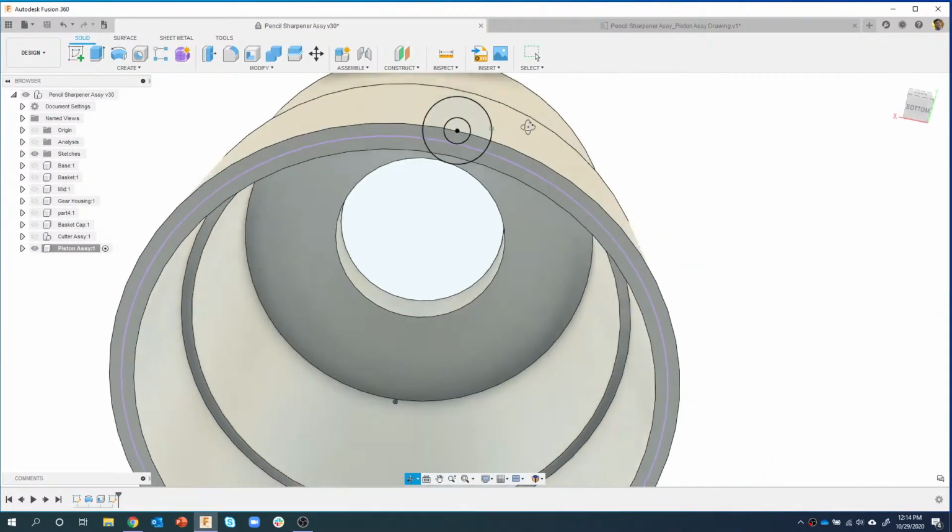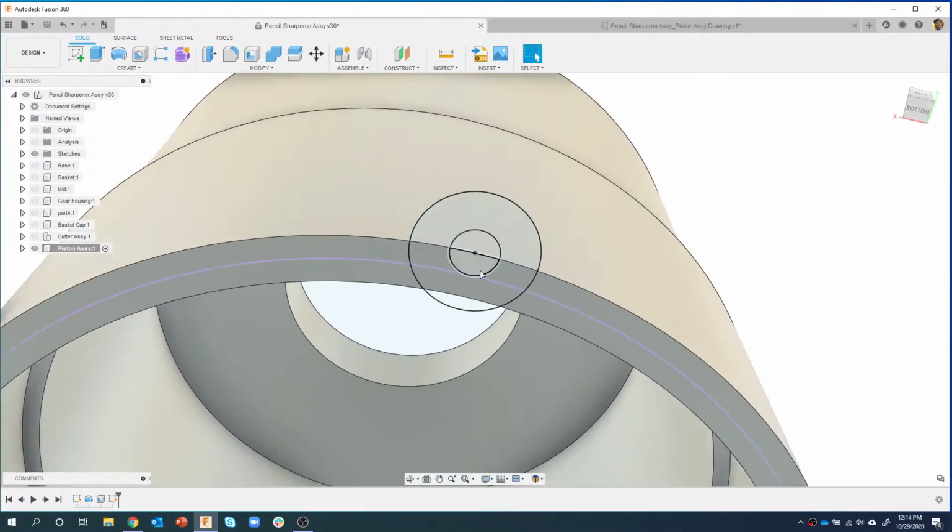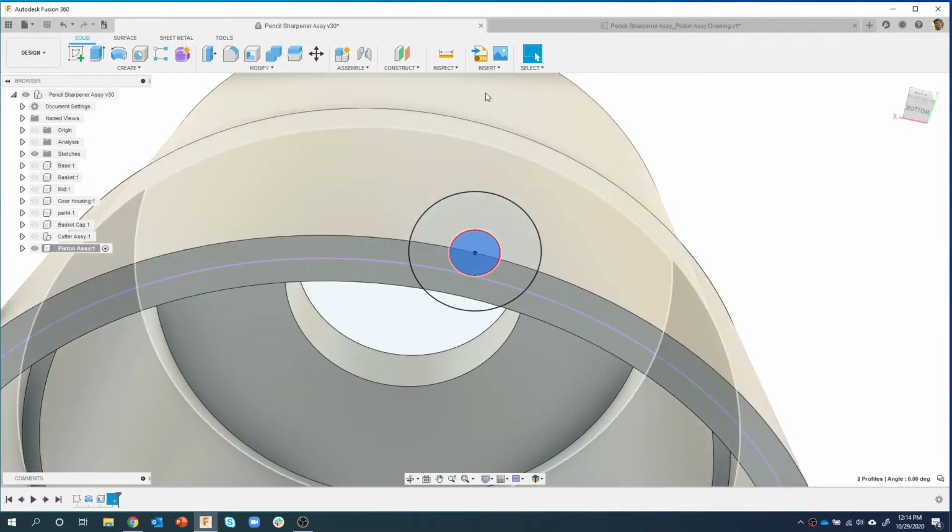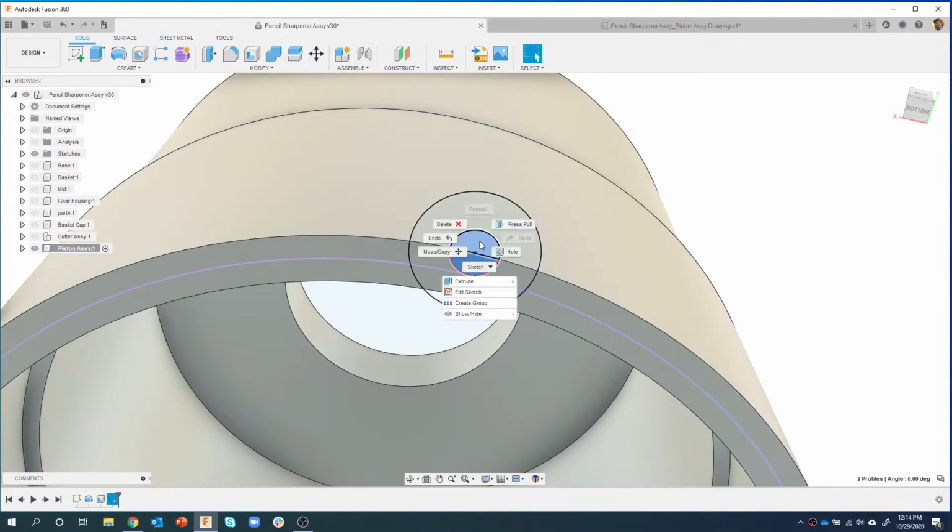Okay, so as I rotate here, you'll see I can go ahead and select. Now, all I really need to do is to select this profile, but I personally, I don't know if it's just me, I like to select both of these to make sure I'm physically cutting everything. If it was just like this, and maybe this face was tapered ever so slightly, it could create what I would call a sliver face. So I like to almost imagine like this is my cutter, and I'm machining it through, and so I'm going to use as much information as possible.